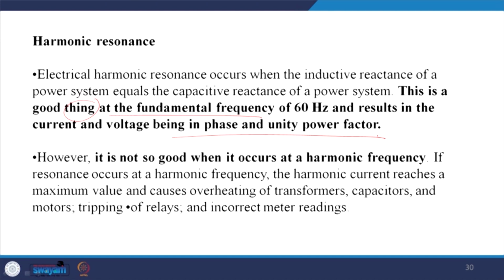However, it is not good when it occurs at a harmonic frequency. If resonance occurs at a harmonic frequency, as I was discussing, the harmonic current reaches a maximum value and causes overheating of the transformer, capacitor and motor, tripping of relays and incorrect meter readings.